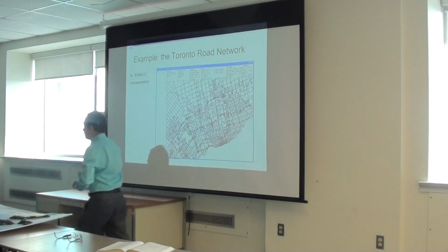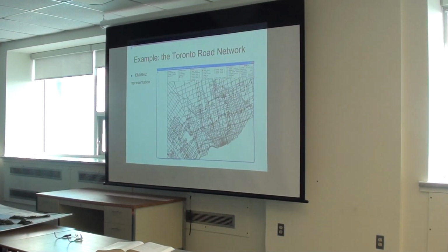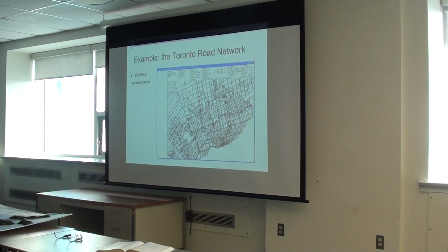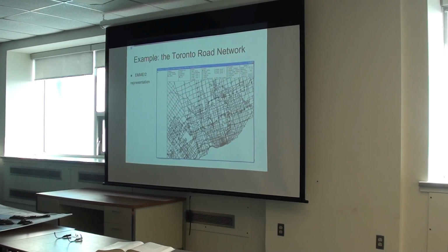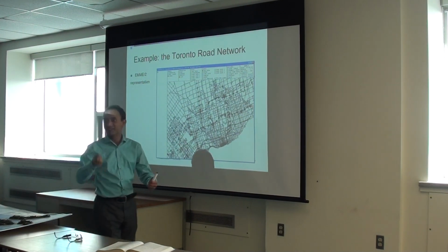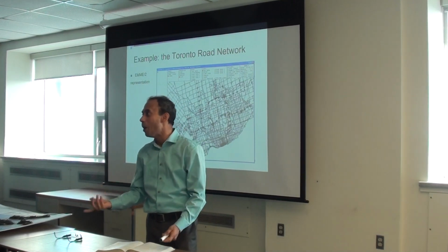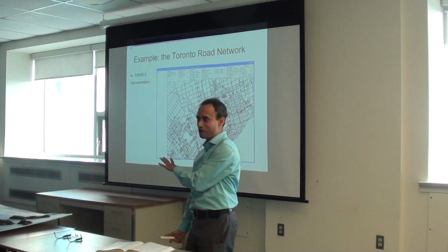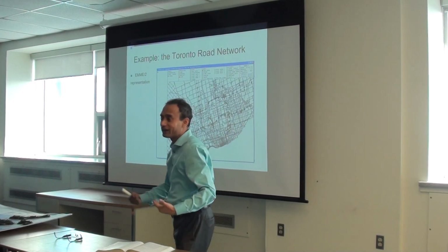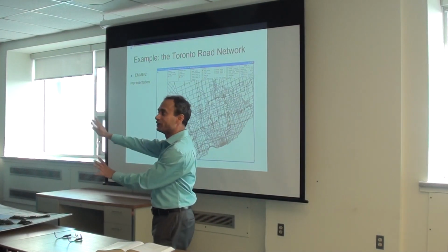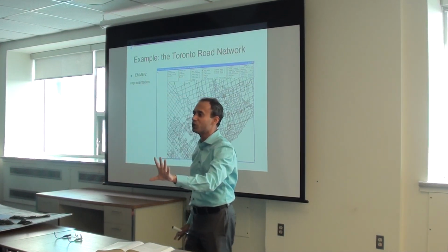We subdivide; for Halifax, we now have 118 zones. Usually we try to go with the dissemination area. I will tell you why: because then we can get data from the census as well. So we just create those zones and assume there is a centroid for each zone from where people start on average, instead of trying to model every home. In our research project we do every home, but not for practical work, like those in industry. So we are still on a zonal basis. These are the two basic principles you need to know at the very beginning.